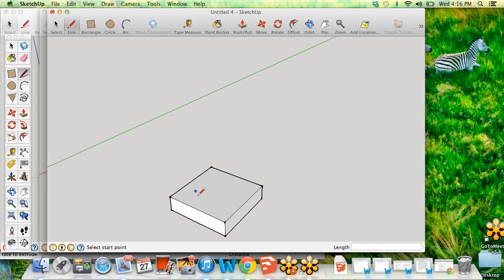We're going to find the middle by going from the midpoint to the midpoint, and then click Polygon. You can see that before you click to start, the sides number is in the bottom right corner. You can change it by typing the number of sides. For 4, I type 4 and press enter. I want this to have a lot of different sides as a column, so I'm going to choose 18.